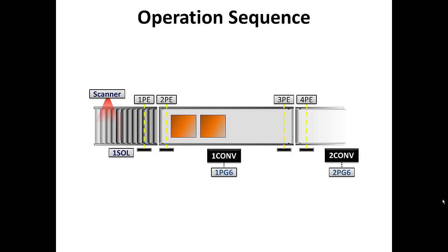So here comes a third carton. Good code, drops the stop, lets it come down against the belt, kicks on and pulls it on. Now if you see this space shrinking between the cartons in my animation, don't worry about it. It's just a function of the software I'm using, and I'm not going to spend hours to make it look absolutely perfect. So if you see the space vary a little bit, you get the general idea. Okay, now the fourth carton comes along, has good code, the stop drops, lets it slide down to the belt, kicks on and pulls 4 cartons on.